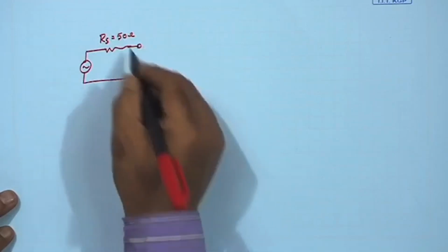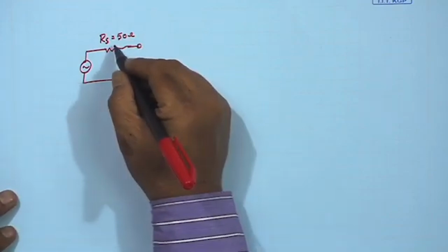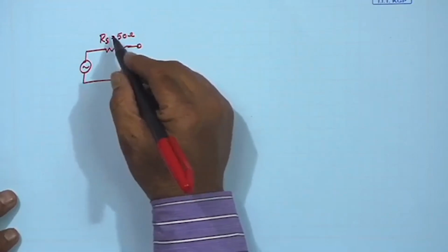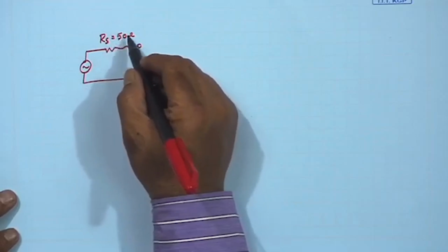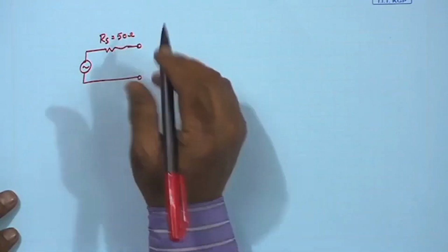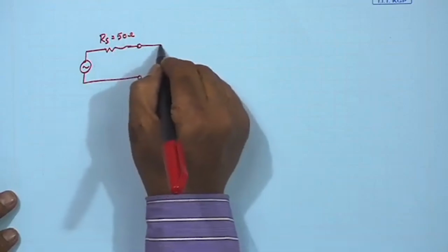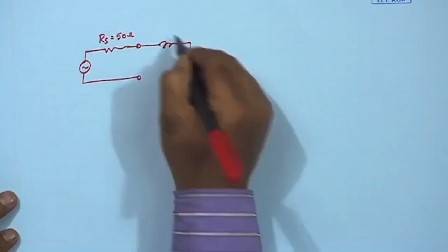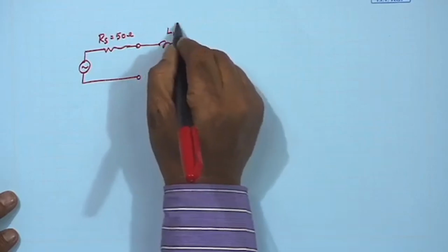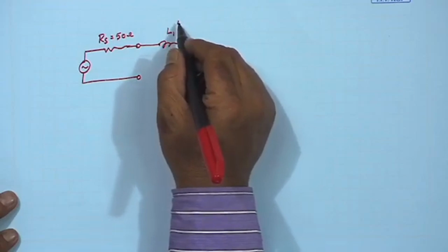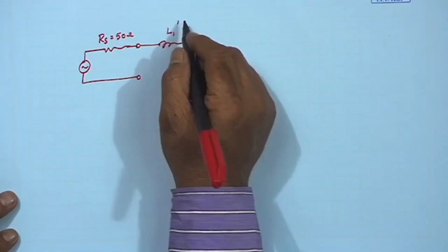This is a Butterworth filter. In the prototype it is assumed as 1, that means G0 is always 1, but here it is 50. So, we need to scale with 50 at the appropriate time, that means our unknown value multiplier will be 50, and then we know the first element we can choose as L1. So, let me call L1, but since it will be scaled both in impedance and in frequency, the type is the same.